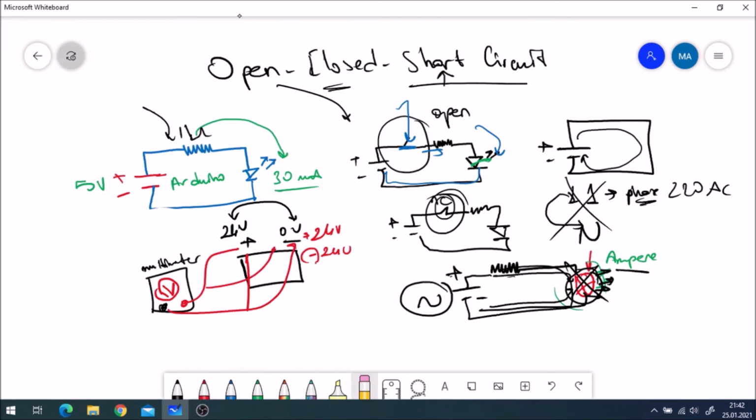But if you forget to switch to voltage, and the multimeter is in short circuit mode, you will see this sign, or another sign can be applied to the multimeter. It doesn't matter. If you forget and leave the multimeter in short circuit mode, and you put these two probes here, what will happen? Your power supply outputs are going to be burned. Why? Because 24 volt will directly touch 0 volt. Plus and minus directly touching together will damage your component.